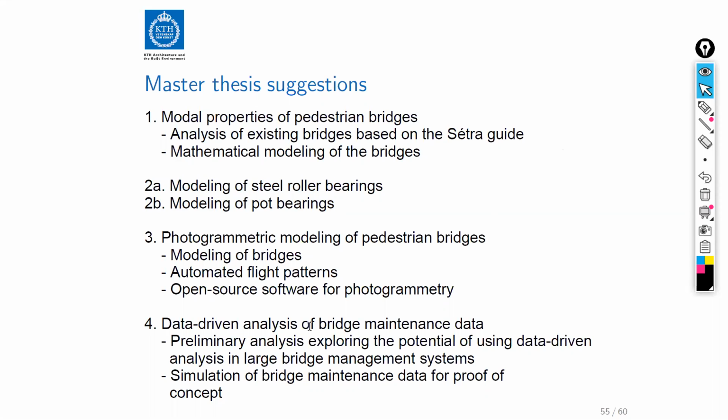We are also working much with photogrammetry for the time being, and we are very interested in modeling pedestrian bridges with photogrammetric modeling. So if somebody is familiar with these techniques and thinks that you would like to apply that on bridges, this is a great opportunity. This is about creating essentially building information models from photogrammetry. So we fly with a drone around the structure and take a lot of pictures, and then we build a model of the structure by triangulation in those pictures.